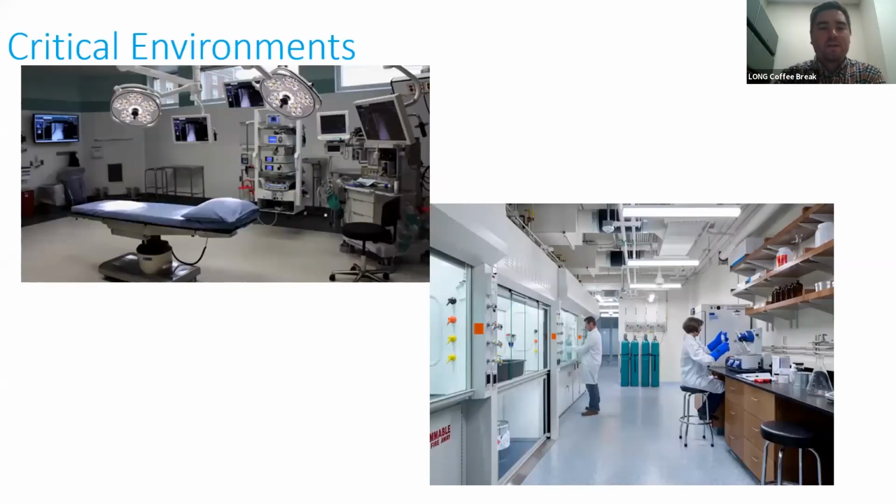So let's touch base on what our main two types of rooms are. You have your positive pressure rooms and your negative pressure rooms. A great example of a positive pressure room is an OR, some sort of operating room, a clean room, sterile room, or protective isolation room. A negative room is going to be your laboratories, infectious isolation rooms, something along those lines.